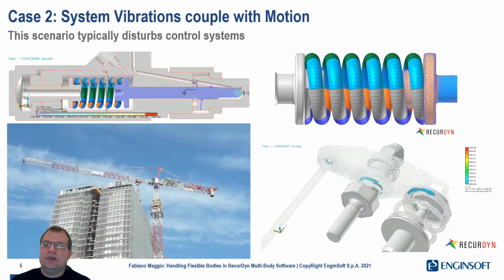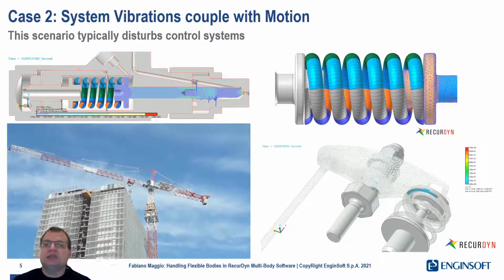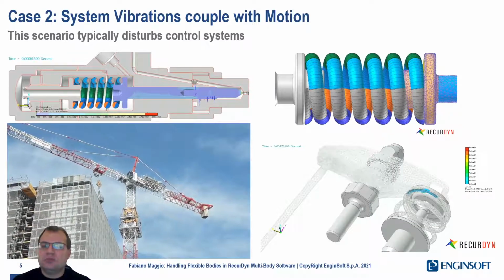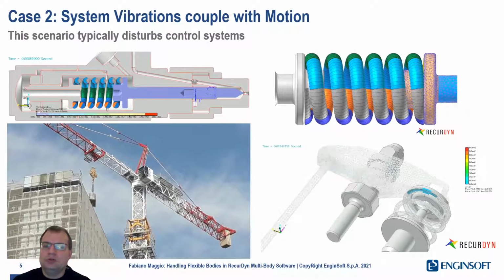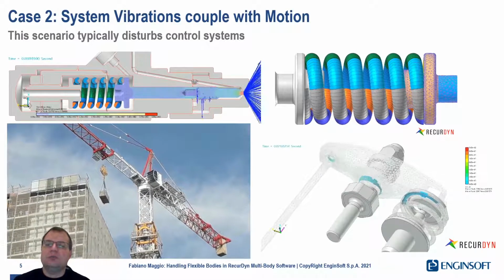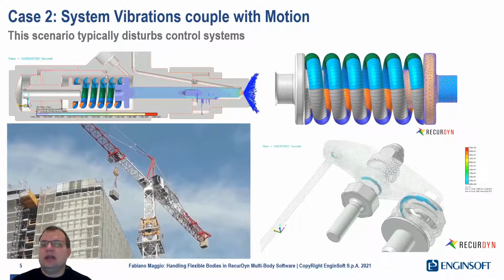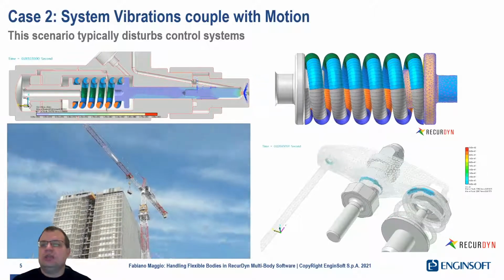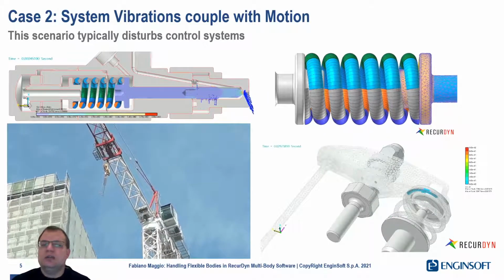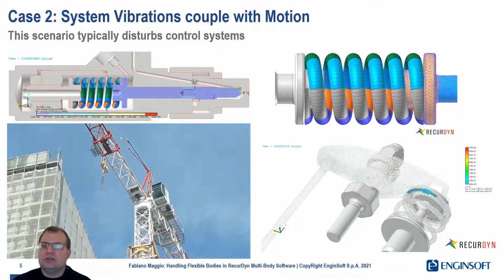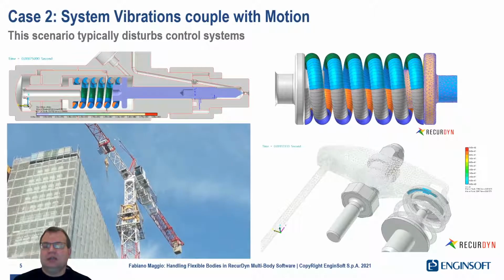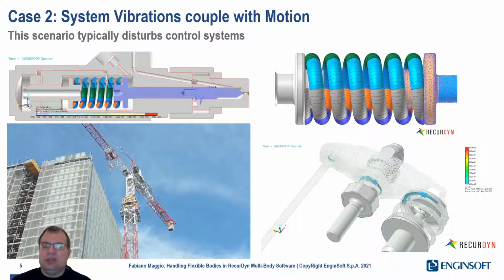When you activate the motor, which is at the end of the tower and at the connection between the tower and the arm, you start applying the load, the torque to move the arm. Then the end of the arm, which might be 50 meters away, is still standing even when the tower starts moving because of the flexibility.